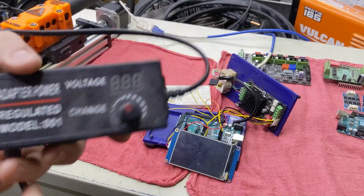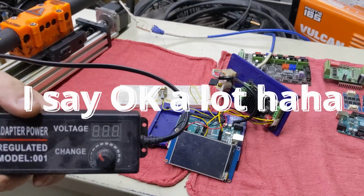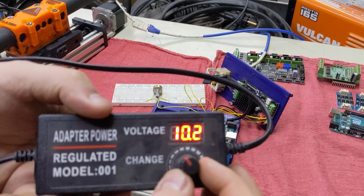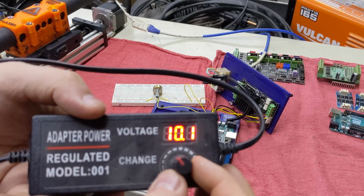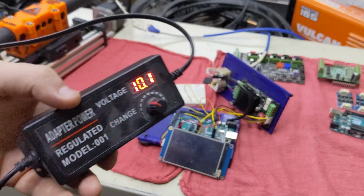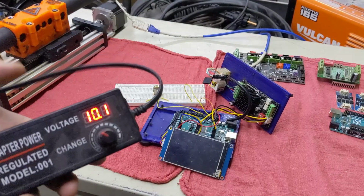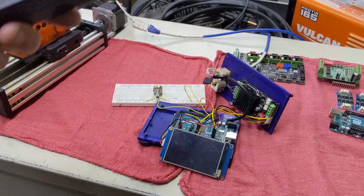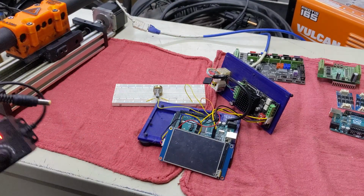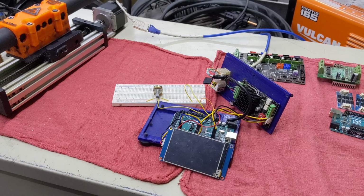Okay, power cable, plugged in. Okay, we want this to be 10 volts, about. No higher than 12, or you're running the risk of frying your board. That's always a fun thing to do at first, and then it is not so much fun after that. So 10 volts, and around 5 amps.